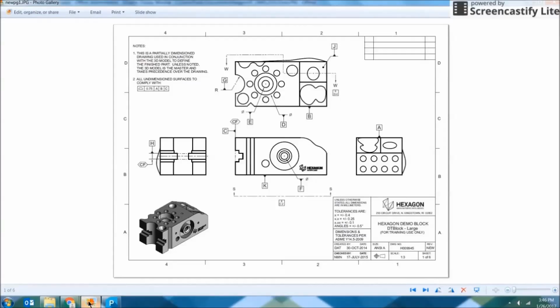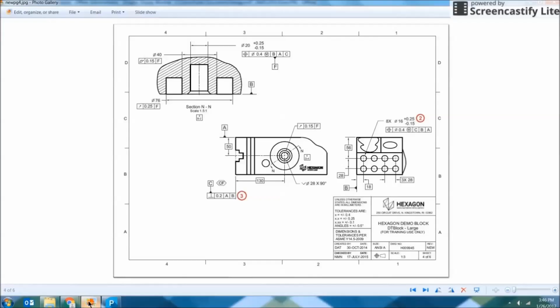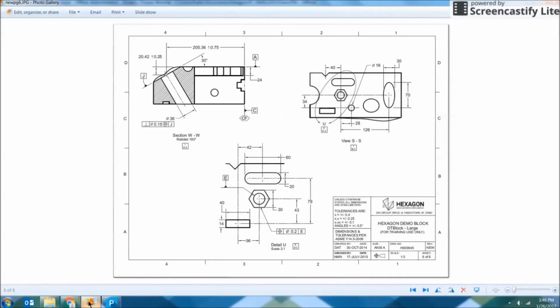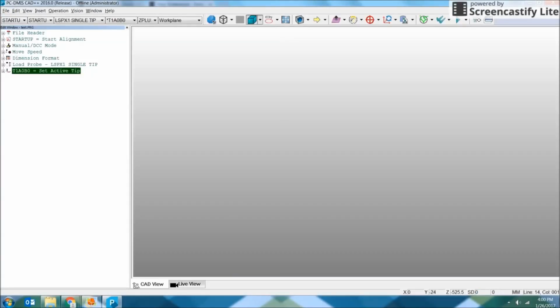Here you can see that my potential customer has indicated for me what dimensions he requires CMM inspection on. Traditional bubble print drawing. So let's focus on how we would capture that data with PCDMIS. If you haven't seen PCDMIS before, I'll give you a brief tour. Over here on the left is our edit window. Contained within are the commands that make up a PCDMIS measurement routine.